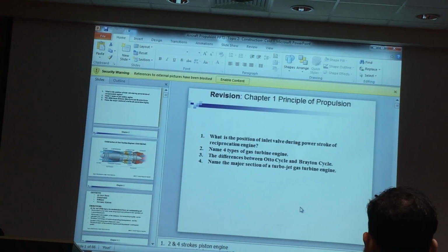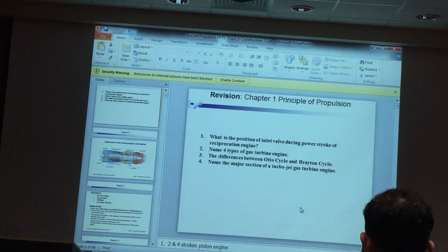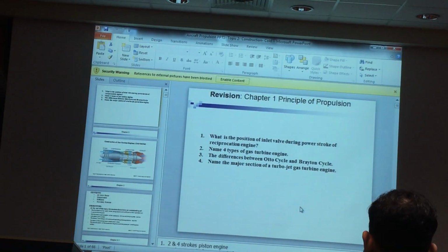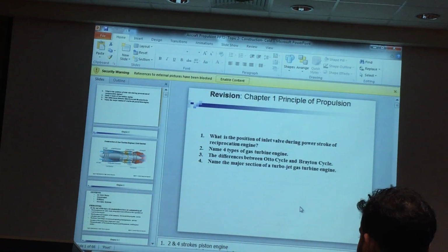Be careful of this. They call it fan inlet pressure, but in GE, the fan inlet is called compressor inlet pressure. They don't call it fan, they call it first stage compression, because the first stage compression is actually the fan. So be careful on the terms used.